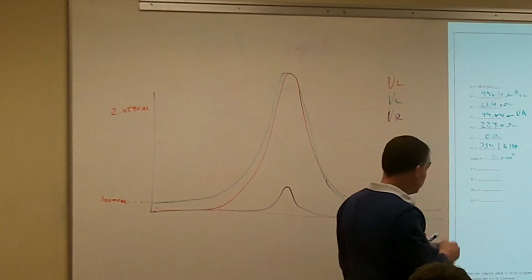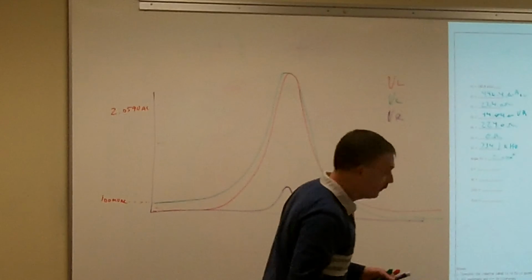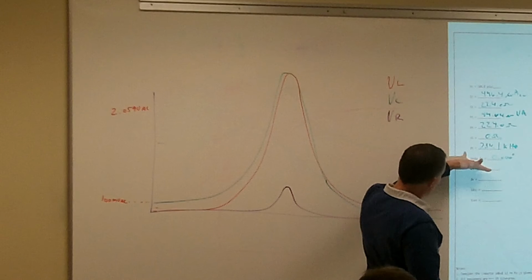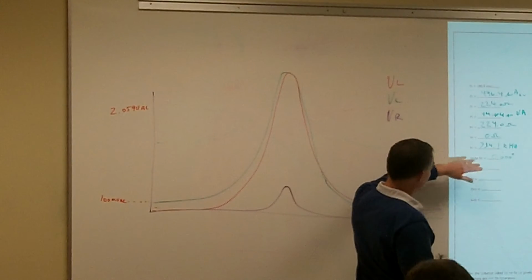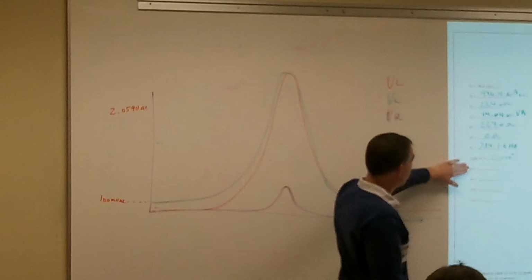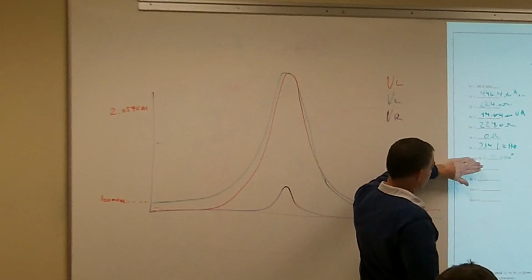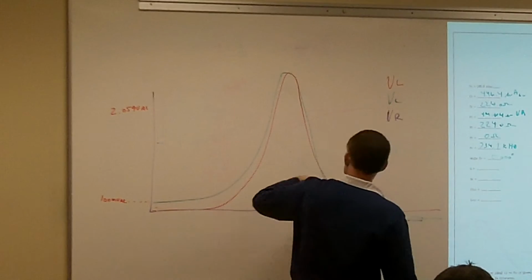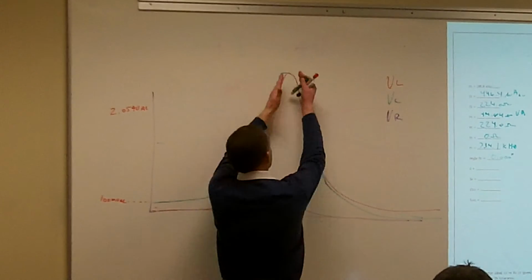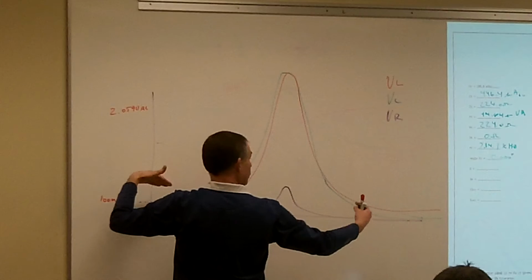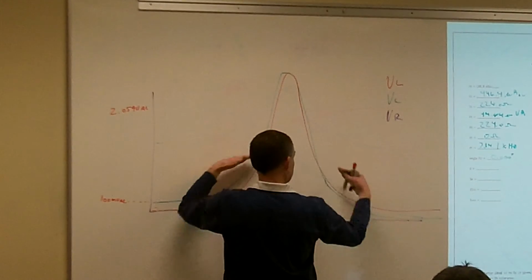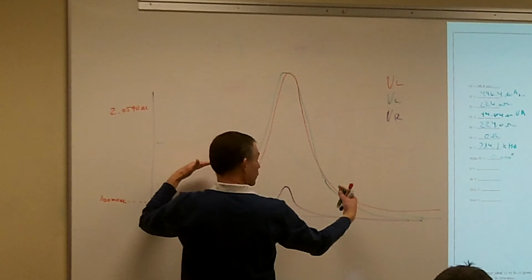Now there are a couple things that we want to take a look at. First of all, we want to find out what the quality of our circuit is. When I'm talking about the quality of the circuit, that has to do with the relationship between our reactance and our resistance. And that quality is going to affect how sharp of a point that is. If I have something that has a large amount of resistance in it, this thing gets wider. My bandwidth gets wider and so on.